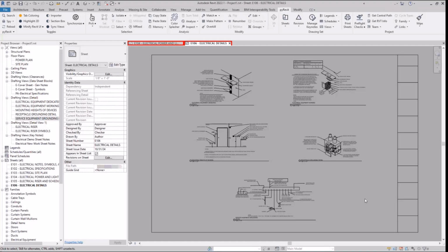For example, say the owner doesn't like using PVC for a specific type of piping. You want to make sure that a detail you pull in isn't referencing PVC piping, because clearly it's going to be a problem. Your drawings say one thing, but your specs say another, and contractors don't necessarily look at the same thing.